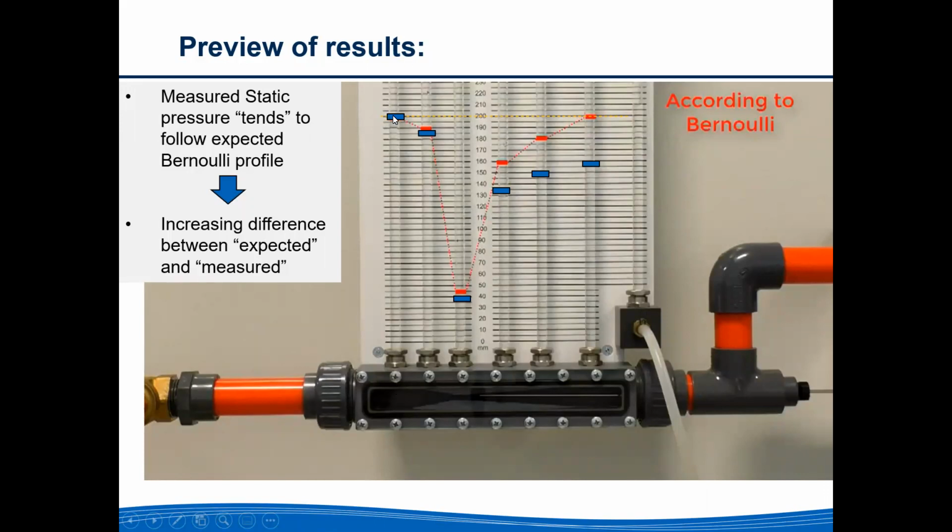Starting with a certain pressure, energy is not lost because Bernoulli's theory is for an inviscid fluid. So the fluid will be accelerating, and the increase in velocity causes a decrease of local pressure. Then in the divergence, pressure usually builds up again, and we have the same pressure at the beginning as at the end. This is according to the theory of Bernoulli.